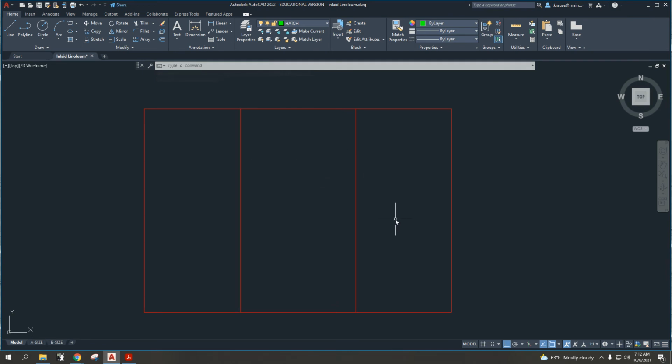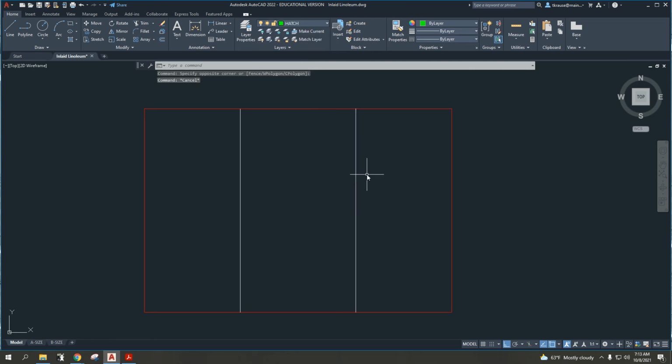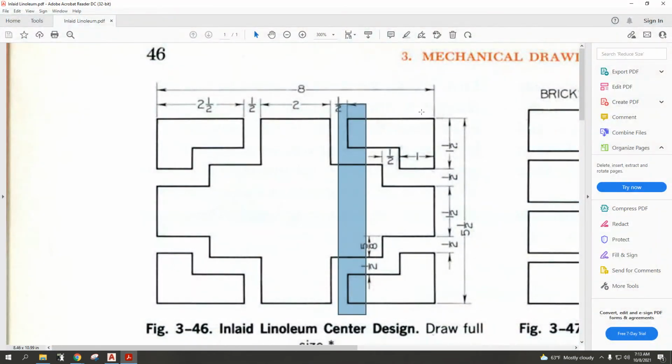Another technique, because sometimes we can get a lot of lines when we're doing this geometric construction. We're projecting things, and we might have to find intersection points where things are located. Sometimes people find there can be a lot of lines here, and they can be confusing. One of the things that might be a good technique is to select lines, and we can put them on another layer. And I would suggest that you use this construction layer. This construction layer is going to be a different color. It just helps you differentiate what's going on, because again, they can get kind of confusing.